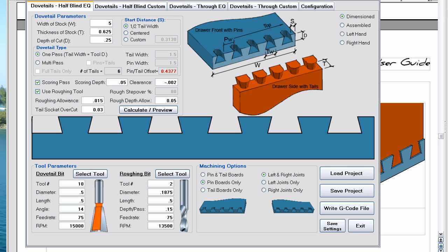And the reason for that is if you don't want to cut them at the same time, then there's no real need to try to make a spacer that's 437 thousandths of an inch, when we can just put them against our fence and mount them at 0.